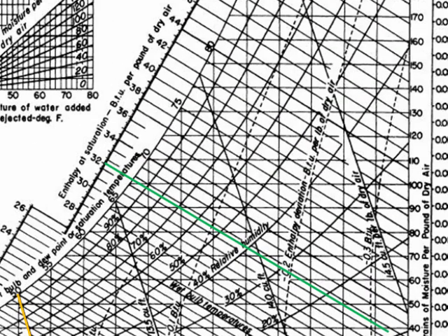Enthalpy of saturation lines are almost parallel to the wet bulb lines. That is why we do not see the slight difference and think they are exactly on each other. The value of the enthalpy of saturation is read on the scale that you see here, and for example, for the line shown, the enthalpy of saturation is 32 BTU per pound of dry air.